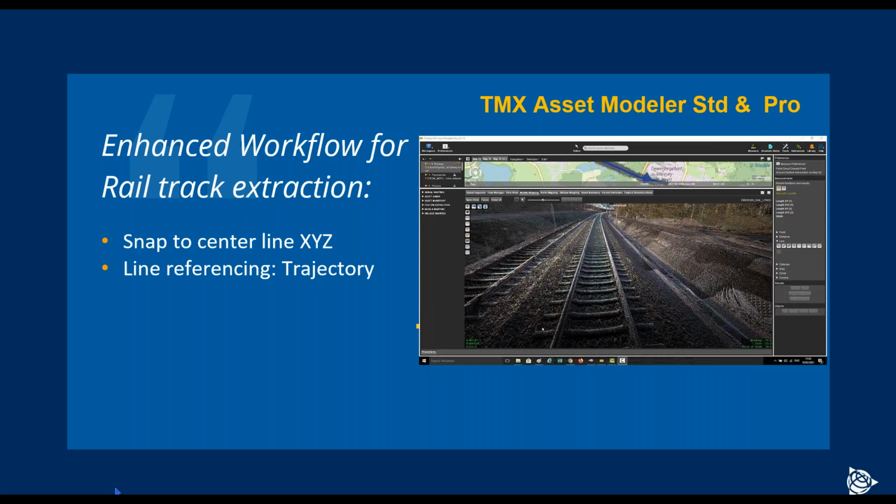And now it has been enabled that the tool is following an already extracted feature, aligning it perfectly in XYZ. I will show you it on a video. The big benefit of it is you can extract a very long linear object like a rail track, right? It's long, and you can extract it with only 3 clicks, saving effort and time and obviously cost.